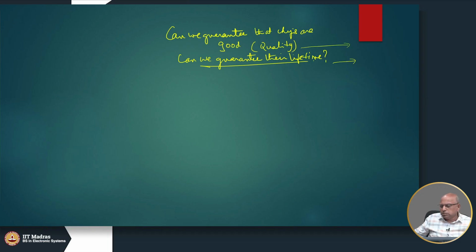So, as a result, producing the masks, etc., and reproducing the features exactly the way you want, will be very difficult. So, bridge faults had to be introduced, and then later you introduce transition delay faults because of all these vias that I talked about, high resistance vias and things like that. Okay. So, as we discover more problems, new fault models have to be introduced.